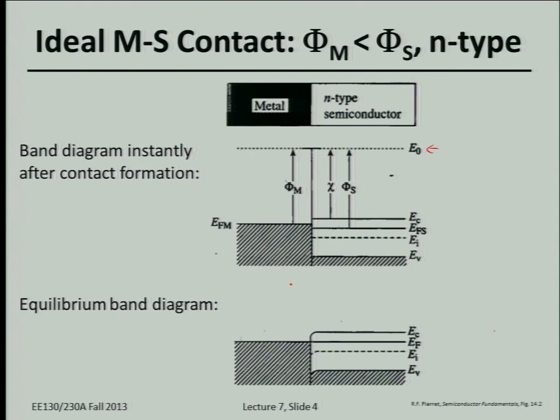Okay, so just qualitatively, if the work function of the metal is smaller than the work function of the semiconductor, in other words, the Fermi level is higher. Is that right? Did I draw this? Oh yeah. Well, it's easier to remove electrons from the metal than it is to remove electrons from the semiconductor. Which direction do you think electrons are going to want to flow when the two materials touch? Semiconductor, that's right, because the Fermi level actually determines the electrochemical potential of electrons. So if the Fermi level is lower starting out on the semiconductor side, electrons will want to go over to the side where they have lower electrochemical potential. So right after touching, electrons will want to go to the right. But what will happen when they go to the right?